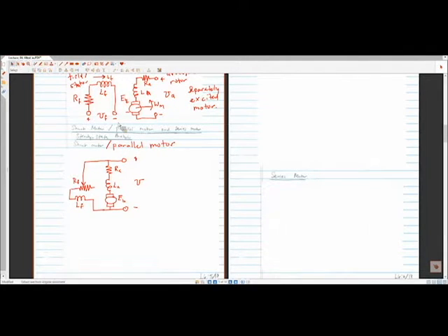So the field circuit is composed of a voltage source and, as in the separately excited motor, a resistor and inductor corresponding to the windings of the field coil. Instead of having this independently driven, we have a single voltage source that drives both of them. The way in which we get flexibility here is we use what's called a variable resistor. How many of you have seen a potentiometer before? Everyone? Looks like maybe you had it in some sort of freshman engineering class, right?